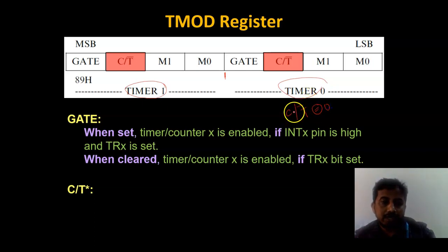And C indicates, whenever you have the uncomplemented form, when it is high, it is active. Low, it is inactive. When you give any input or any pin or any bit in complemented form, just like T bar, it is active when you give it as 0. It is inactive when you give it as 1. That is the most important thing you need to remember.